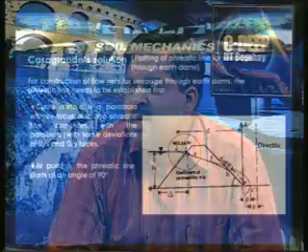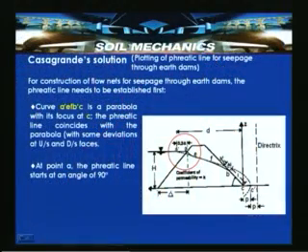but in this particular Casagrande's solution, to some extent both entrance and exit conditions have been treated correctly, so that we can arrive at a very representative phreatic line which may occur in the field. So curve A dash E F B dash C is a parabola with its focus at C.